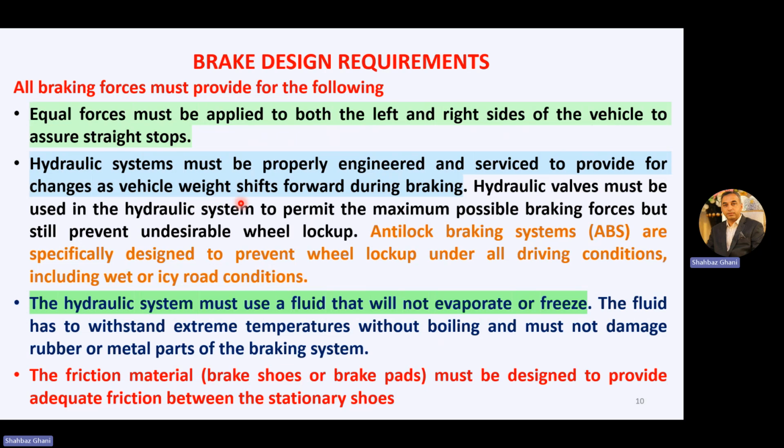Hydraulic valves must be used in the hydraulic system to permit the maximum possible braking force, but still prevent undesirable wheel lockup. So your hydraulic system, and especially the hydraulic valves, should be designed to provide a braking force that prevents undesirable wheel lockup. Normally, we have this wheel lockup problem in vehicles which are not equipped with an ABS system or anti-lock braking system.